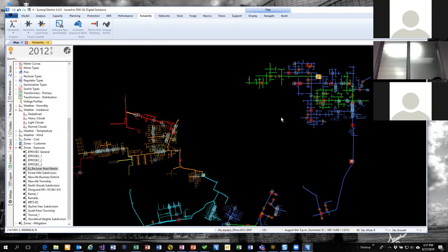You could see that flicker on the charts now, and it's not going to be in 6.4, the next update, but we are working on the PST, the short-term and the long-term flicker values, which is a kind of sliding filter that would give you numbers so you could look at this customer and say their flicker is okay or it's not okay. But you can certainly simulate the flicker.